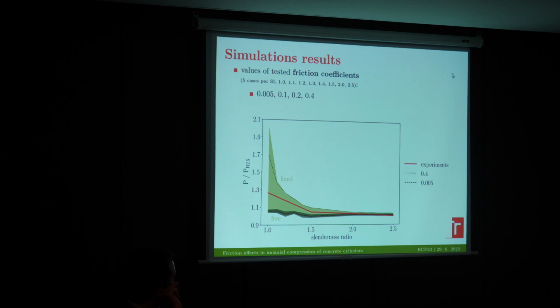On the other hand, for extremely small friction coefficient, you can see that the results are similar to the free simulation. Not completely the same, but it approaches. And finally, there's a value of 0.2, which, as you can see, approaches the real experimental solution. And the last value of friction coefficient, 0.1, we obtained a really nice correlation with the experimental results.